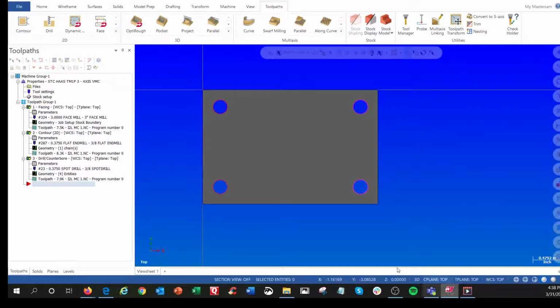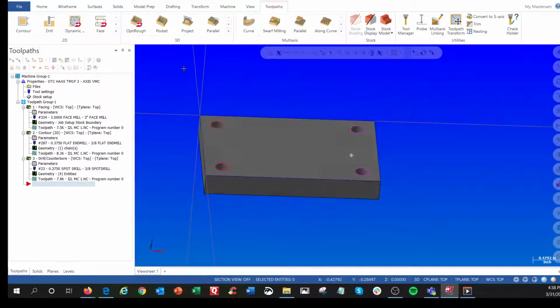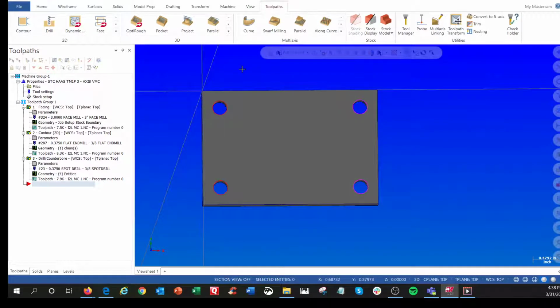So in Mastercam here, I'm going to use this crosshair as our 0 location. You can either draw this up or import it if you already have a digital file, say if it was something more complicated, but make sure you line it up to where you want your 0 to be.